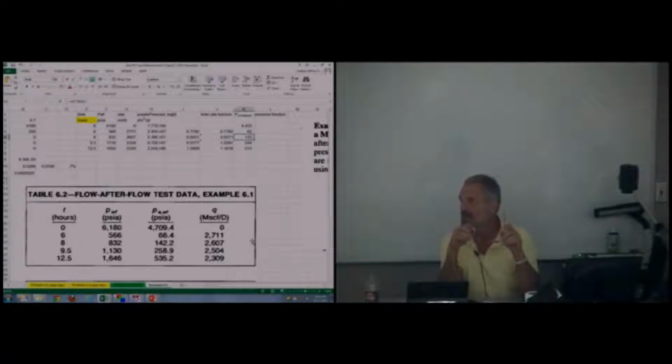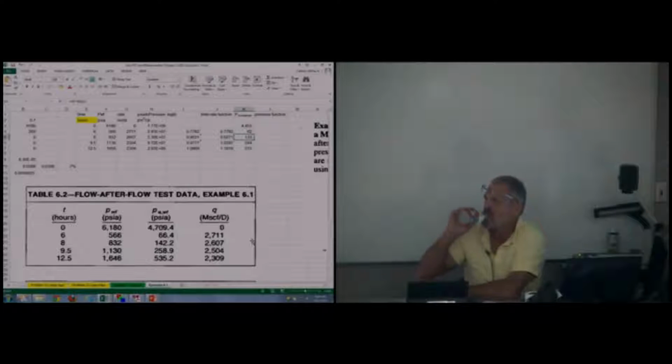When we're all done here, before we leave class tonight, we're going to decide that we don't need to do this, so it's not critical, because we can just do it with pseudo pressure. This is just to make some people feel comfortable, because the normalized pressure numbers are less than 10,000, where the pseudo pressure numbers are bigger than 10,000. They don't like to look at numbers that big. So when you calculated your pressure pairing here, you're just doing that even though it was already given to us?